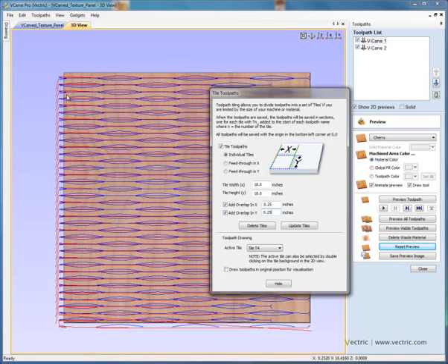This allows us to ensure that the toolpath overcuts very slightly, and then you can very simply create a 2D profiling toolpath to machine around your 18-inch square piece of material to make sure you get a nice sharp crisp edge where the mating faces are.